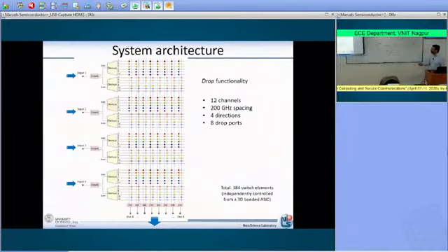go. Anyway, so here you have the matrix of microring resonators. However, you have a first point: you need to separate the different wavelengths that are coming from the input. And therefore, you need here a demultiplexer that is demultiplexing the wavelengths. I'm going step by step later on through the different functions. So then you have your matrix of microring resonators, and then here you have the drop port. So let us assume that you want to send a channel, a wavelength, from this input here to that drop port. Okay?